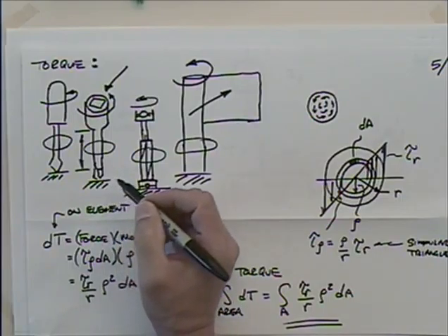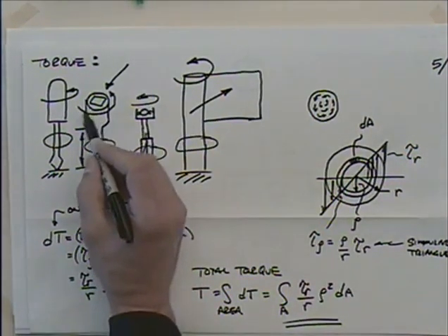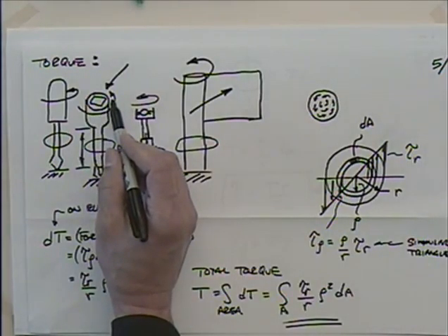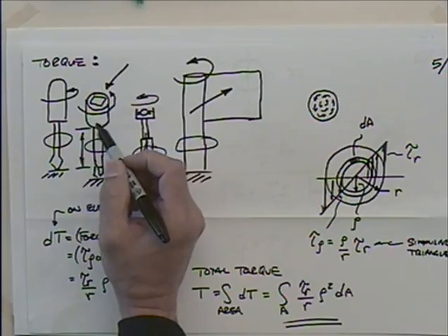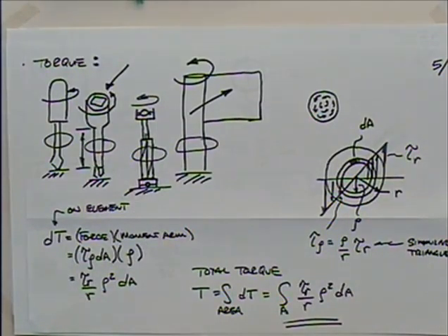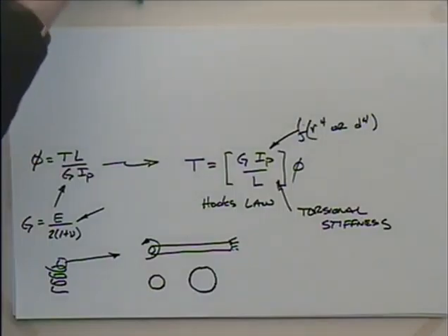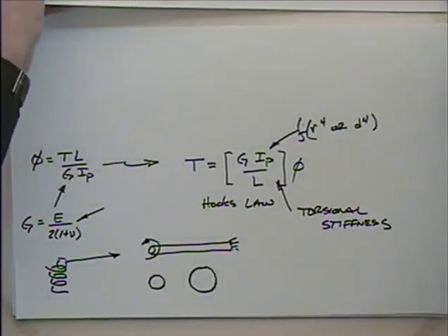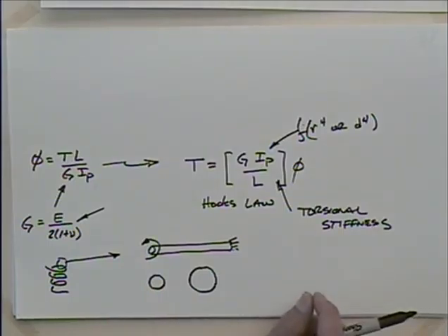If that's 2 or 3 feet long and you start to really put some load on it, you can actually feel it twist, can't you? Sometimes you can use that as a technique to undo a stubborn fastener. You just twist it up and all of a sudden it lets go, right? Hopefully for the best. So as the length increases, the stiffness decreases. Hopefully that makes sense.